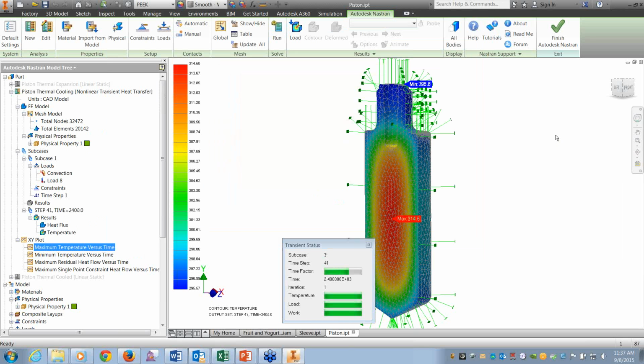What I'm not showing today is how I could run an analysis where I would take a look at how the relative size of this piston and the relative size of that sleeve that it fits in vary with the temperature as well, because we're looking at two different materials, a plastic and a steel, stainless steel. So as that goes up in temperature, am I going to go from a minimal clearance needed for the piece of equipment to operate, this being food industry processing equipment? It's intentionally designed to not use O-rings in the product path, so you don't have anything that could hold material there and possibly get into a sanitary issue.